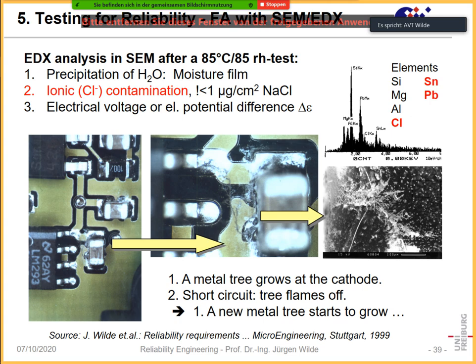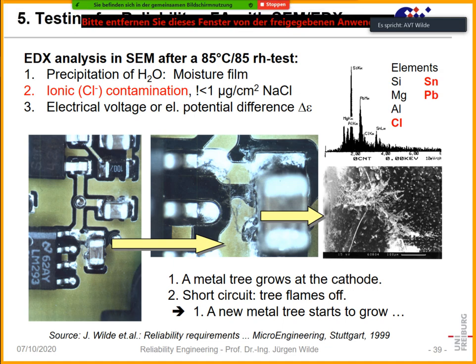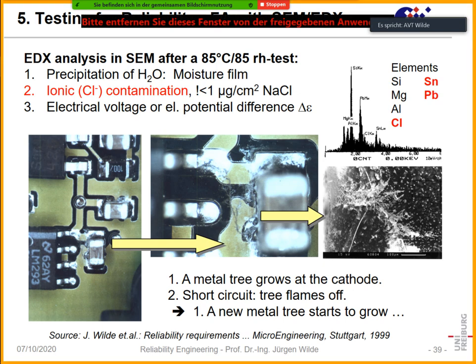And here that was a result of just a laboratory investigation. We tried out what happens in an 85-85 test after we have not coated this printed wiring board. And we had some very strange behavior. In that ECU board we had no failures, but we had faults. So suddenly it didn't work anymore. After some reset, it was operational again. And that was very strange, because it didn't really fail, but it was faulty.